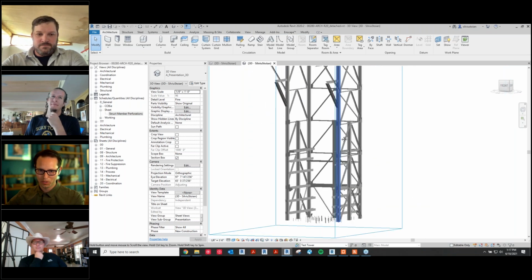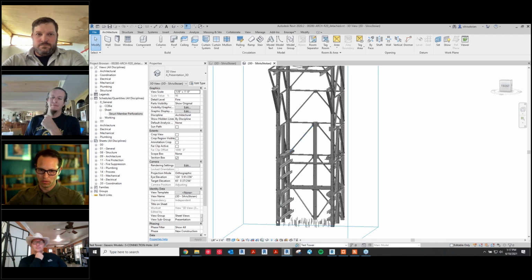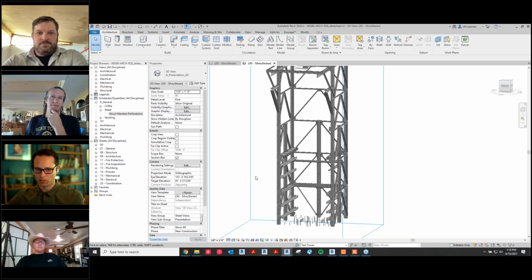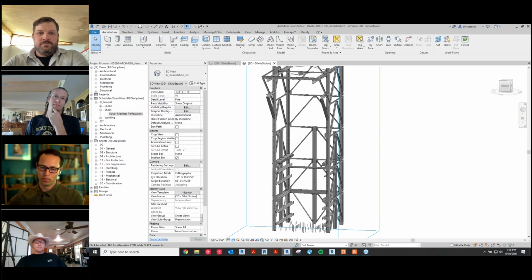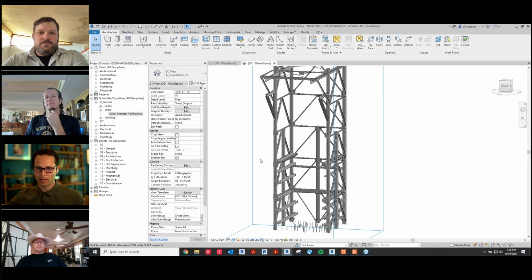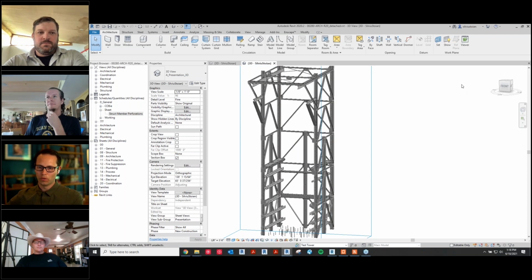This whole structure might not seem like a lot, but it takes so much time compared to just doing an LOD 300 model, exponentially, or maybe three or four times more, if you're doing an LOD 400 model versus an LOD 300 model. So you need to pick very wisely when you sell an LOD 300, let's say not the whole model, but maybe a portion of the building to be at that level of detail, because it can add up and be very expensive.